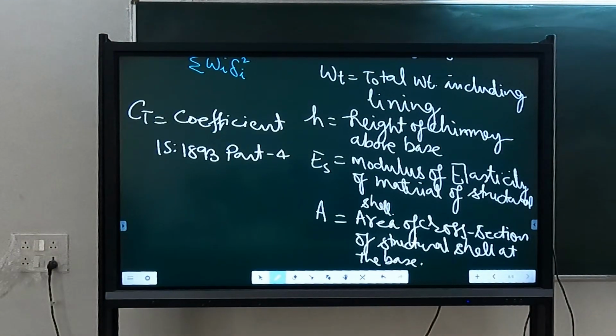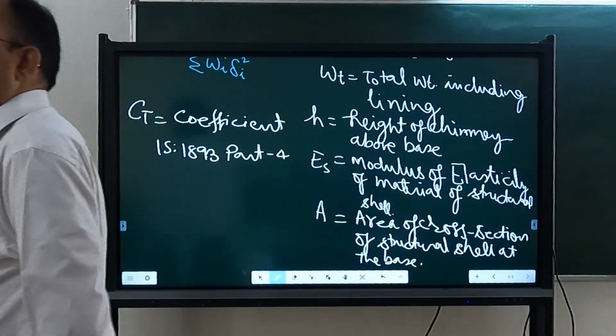This is not hysteretic; that is taken care of by R. Damping depends on omega, the frequency. Damping depends on frequency in some materials. For example, in soil it depends on frequency, but not in steel and concrete. So it is not depending on frequency. Frequency will remain the same.